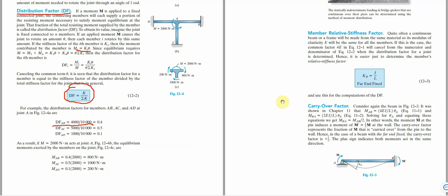And the way we do the calculation for this is very simple. I will explain. For instance, we are considering this beam here, and we said that the moment at A to B is 4EI over L theta A, as we explained the other time, and the moment about this side is 2EI over L theta A, because this side is fixed, unlike this side where we have 4EI. So if you look at the two, this side is 4EI, this side is 2EI over L.